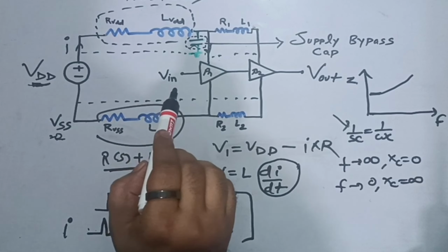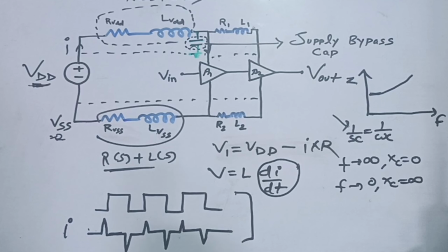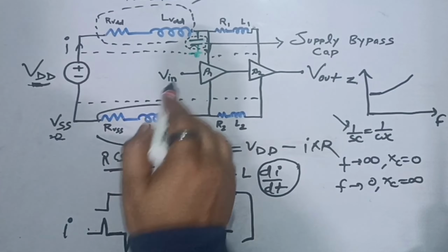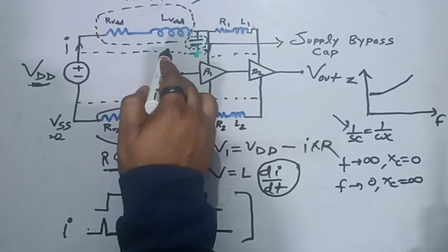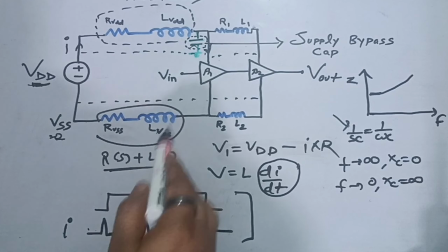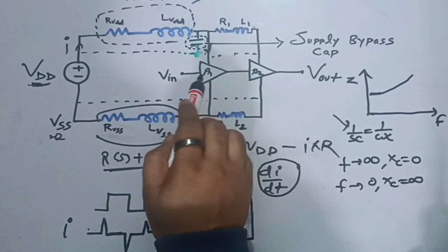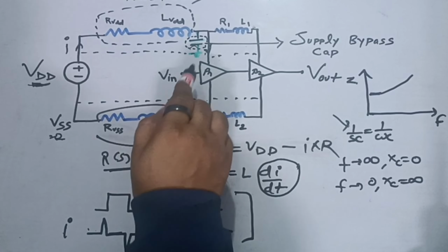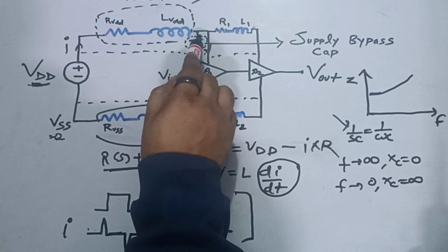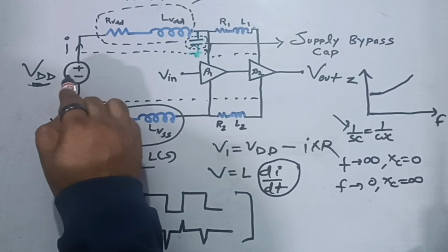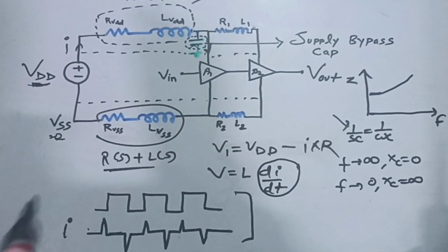It's a kind of power supply rejection ratio method. By introducing a very high value of capacitance, we can filter the high frequency component so that our op amp can work as intended, and at lower frequency the capacitor will oppose current flow into itself. So all the current from supply will go into the op amp, and our op amp will work fine.